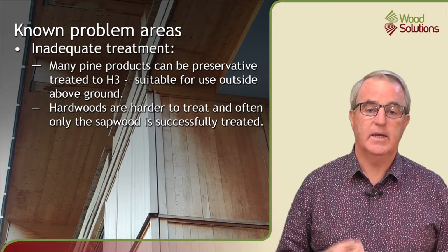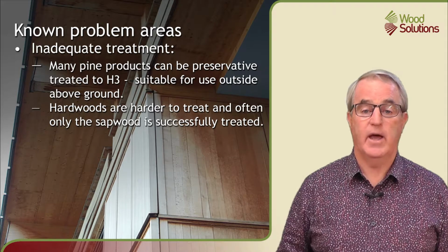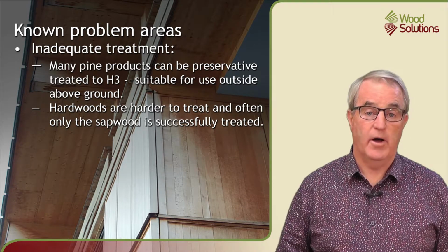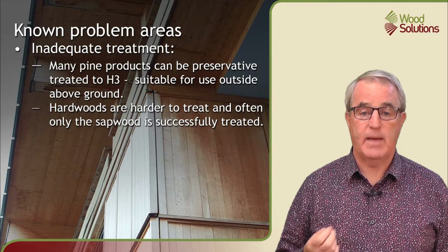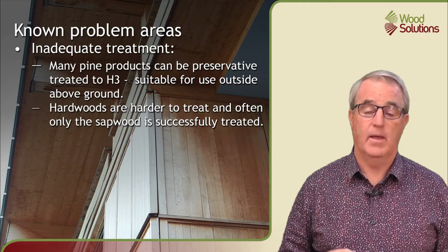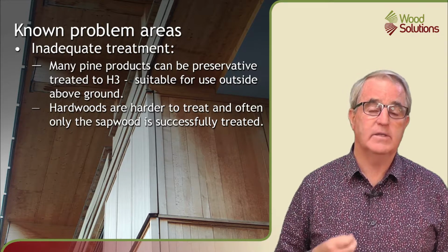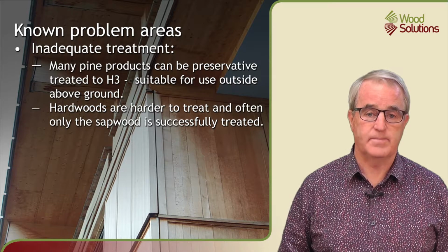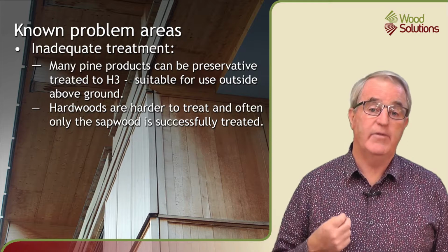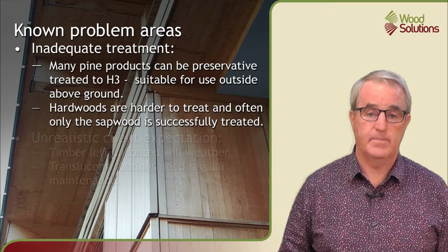Inadequate treatment is the next known problem area. Pine can be preservative treated to H3, suitable for outside above ground. Conventional pine products are often rich in sapwood and can be fully treated, therefore they should perform well. Hardwoods are much harder to treat than pines, and often only the sapwood is successfully treated. Most of the board remains unprotected, and if it has a low natural durability, it can decay relatively quickly.